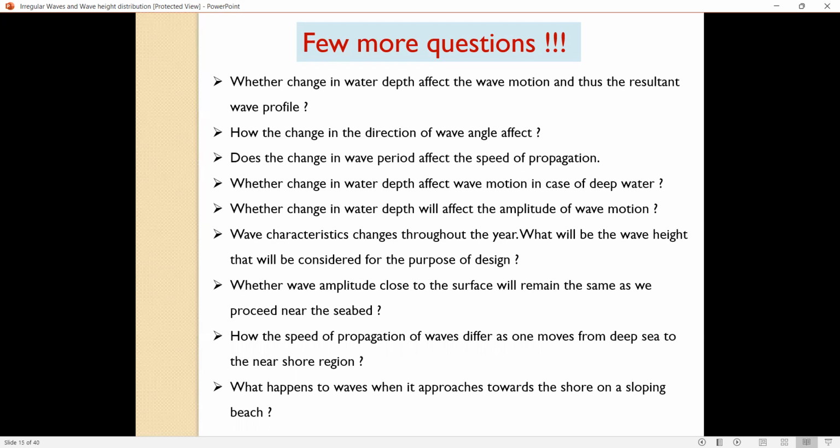Because of depth variation, the configuration changes when you look at the coastal area, the shape of the coast is changing. So that will lead to a class of wave refraction problems. And then the depth is varying. You can say the water depth is varying, the stratification is changing, the density variation is there. All these will lead to the wave propagating from one medium to another medium. When you say depth is changing or the stratification, the density is changing, you can say we have one layer of fluid moving to another layer of fluid. In that case, the concept of refraction is borrowed.